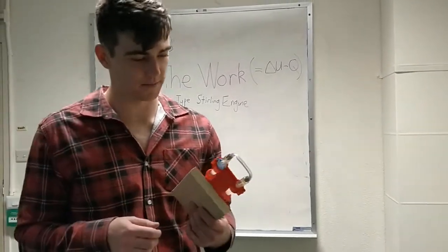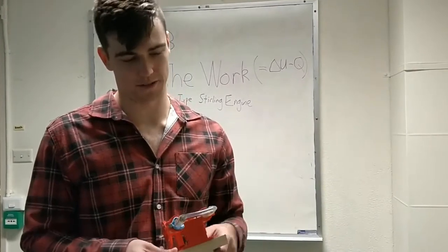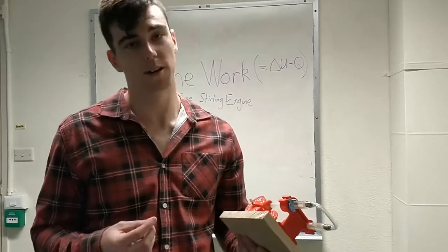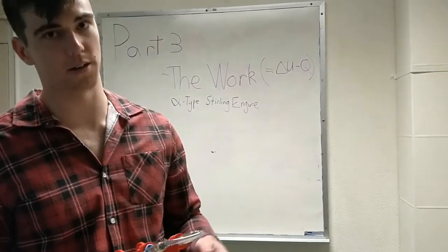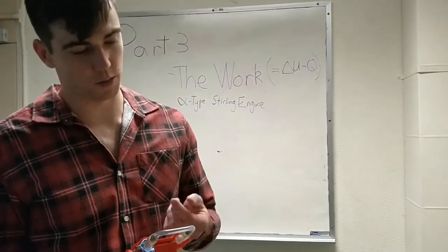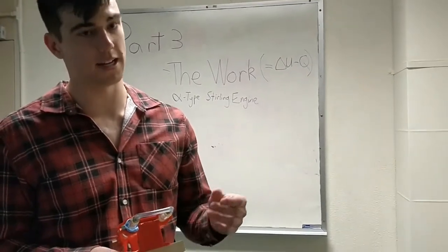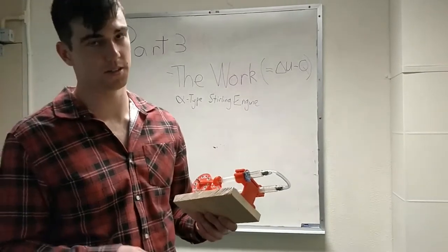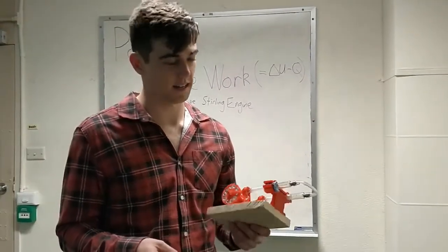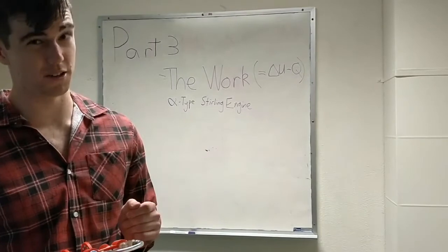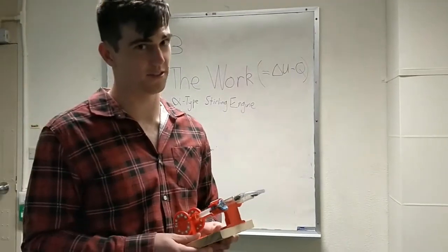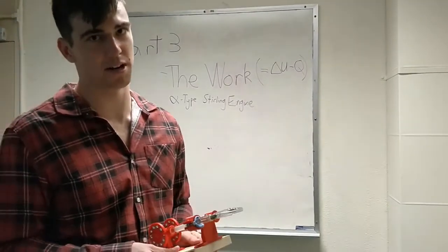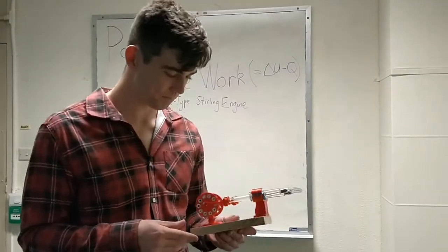The tube here at the end was a more difficult part, as it had to be completely sealed around the syringes to reduce air loss, which would decrease the efficiency of the engine as a whole. How this was dealt with was with a piece of 9mm tube and a heat gun, slowly and gradually stretching out the tube until it went over the ends of the syringes, creating an airtight seal. During construction, this was one of the biggest difficulties. It took me probably 4 or 5 different tries to be able to stretch the tube out without having it pop and burst and inevitably have holes in the seal.